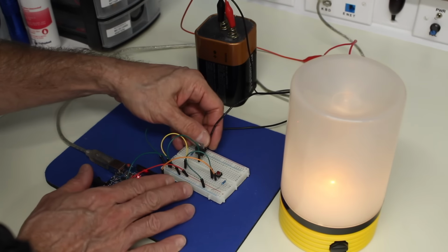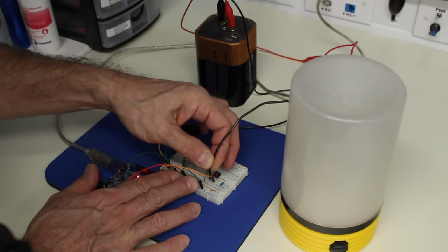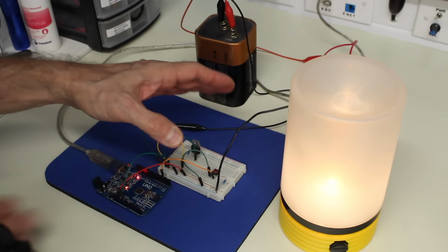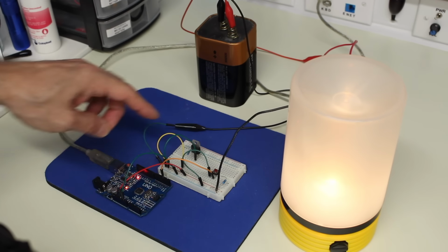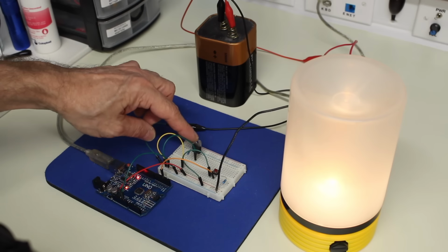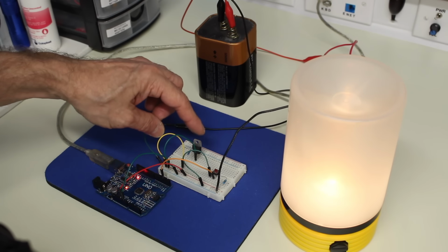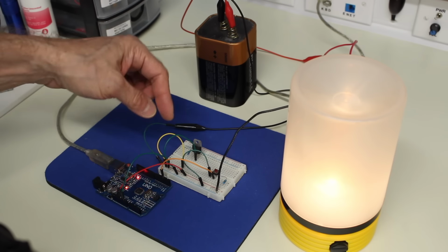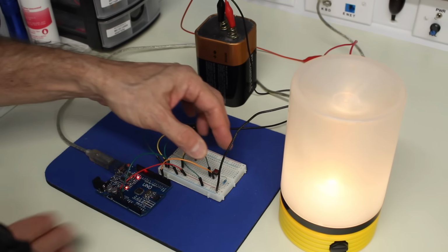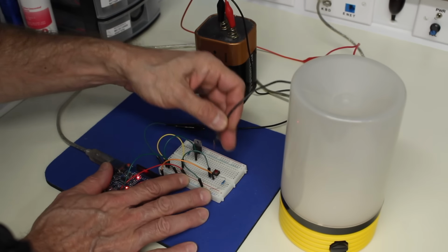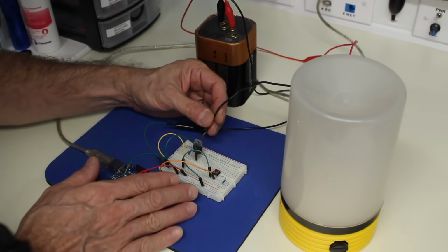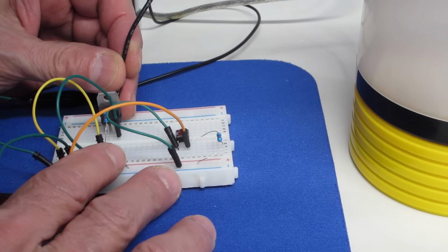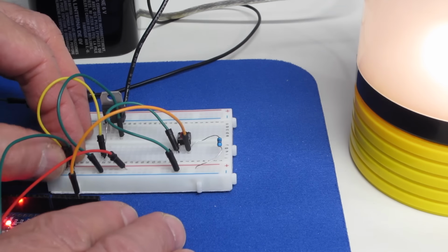I'm going to disconnect it from the transistor for a moment, and I'm going to just put it back on the negative rail. As you can see, that's a lot brighter, and the reason for the difference is the voltage drop, the 0.7 of a volt that we're getting through this transistor. That's enough to cause a notable difference in the brightness of the light, so it's one reason why bipolar transistors aren't necessarily the best. I'm going to just put that back, and that should be my light.